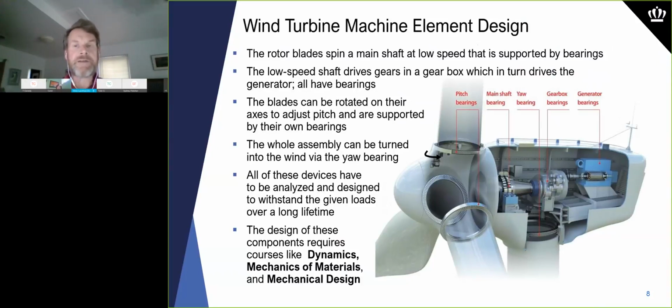At the far right of the wind turbine, you see there's some instrumentation here. There's actually a little vane that tells us what the direction of the wind is, and there's a little spinning anemometer here that gives us the wind velocity. So based on those measurements, we're actually going to adjust the pitch, or how the blades are facing the wind, about this bearing labeled as the pitch bearing. So we actually twist the blades based on that reading. We're also going to rotate the turbine housing, the whole thing here, which is known as a nacelle.